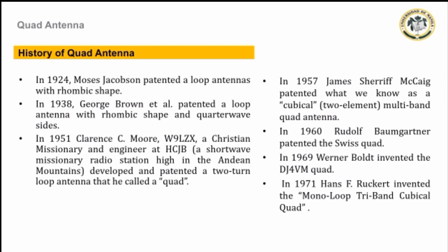The length is not critical, typically from 1 to 2 wavelengths, but there is an optimum angle for any given length and frequency. A horizontal rhombic antenna radiates horizontally polarized radio waves at a low elevation angle off the pointy ends of the antenna.